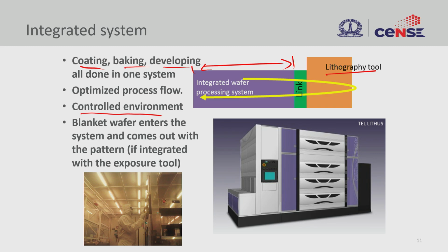In case you cannot afford this kind of integrated system, still make sure that your subsequent litho processes happen without any delay or with the least delay, and also in a controlled environment. Make sure your temperature and humidity in your lithography bay is maintained.